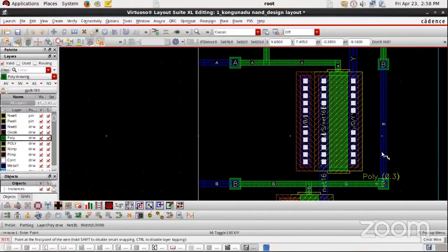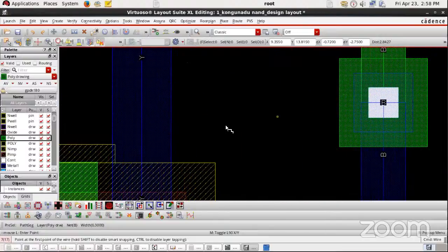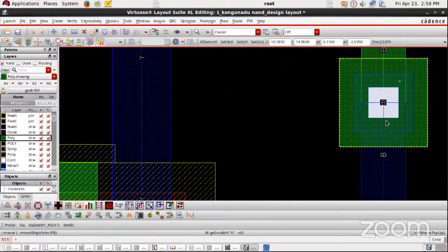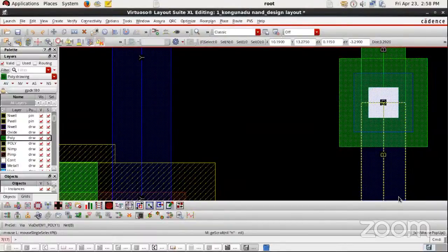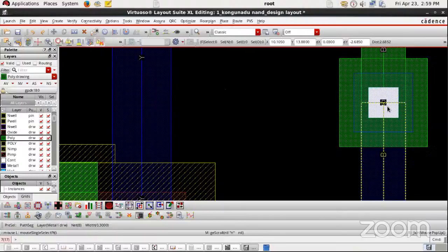wires. Including wires will give rise to parasitic capacitance, because as I have told you, this via is between a metal and a polysilicon. Obviously both are conducting material. Metal one is obviously a conductor, whereas polysilicon will be able to conduct at a certain threshold value. So you have two layers over here, connected with the contact, and they will be separated by an insulating material.